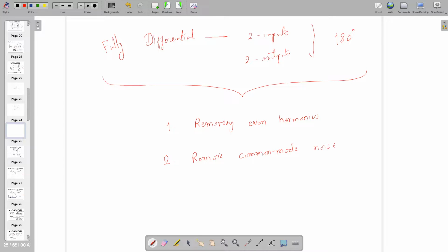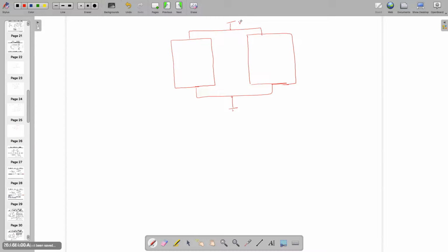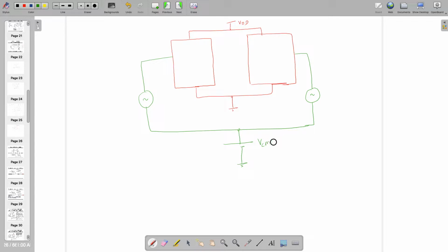And we discussed some of the advantages, and we also talked about one fact that if there is a single-ended circuit, if you want to make it differential, you have to make an exact identical copy. This control C and control V has to be here, like it's an identical copy. There is no difference between these two boxes. They have to be connected with VDD and ground. But while connecting the inputs, both have differential input with some common mode voltage. This might be DC, it might be some other thing also. You can see here,